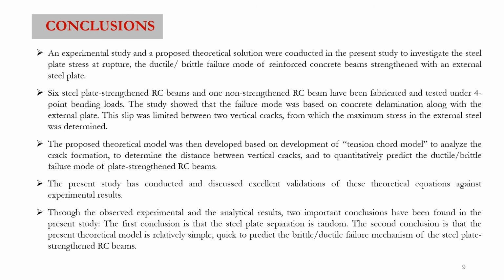Our conclusions are: 1. Steel plate separation is random. 2nd, our theoretical model is relatively simple and is very efficient in predicting the brittle or ductile failure mechanism of the steel plate strengthened RC beams.